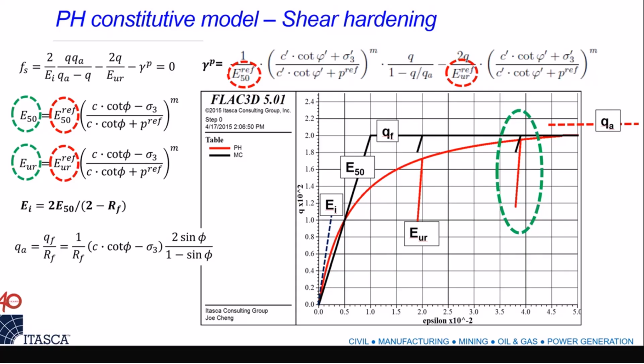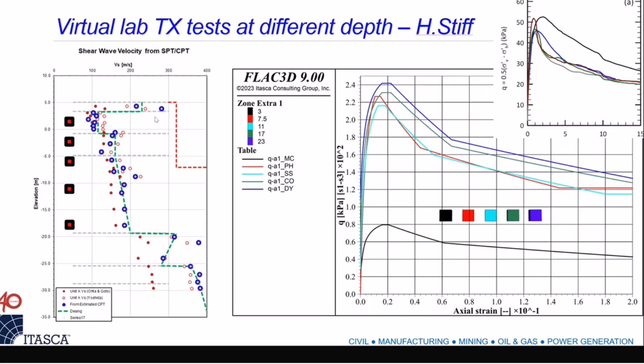And then in case you have a distribution like this, what I did, I developed a strain control plastic hardening model in which each zone checks what the strain level is, and depending on the strain level, updates the shear strength properties so that it can actually follow somehow the softening behavior. Right, and this one can also accommodate a nonlinear strength envelope. This is another topic that is not in the question, but is strongly related to this aspect.